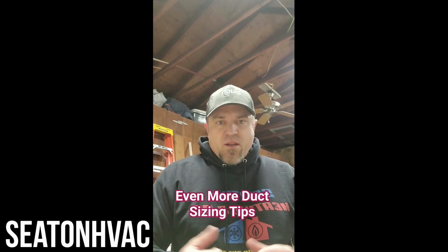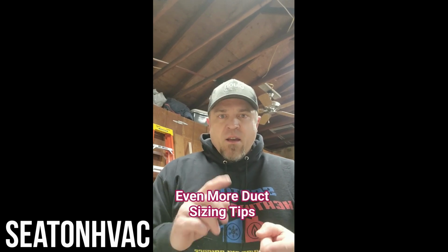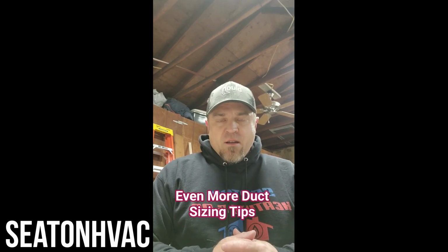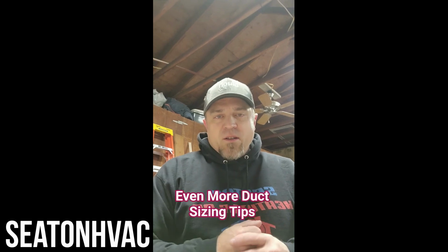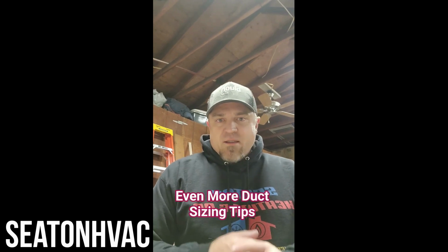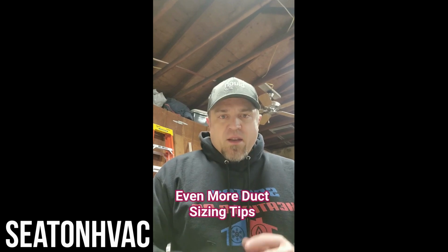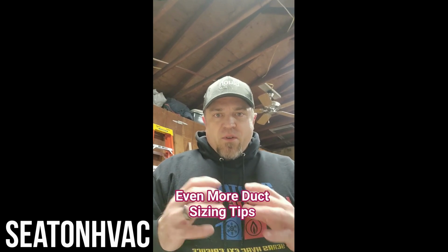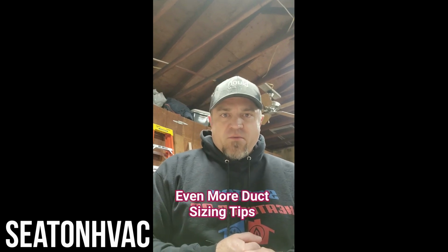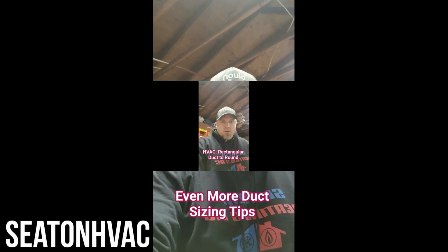So what we're going to do tonight is we're going to have some fun with return air sizing and return grill sizing, and I'm going to show you some things that you wouldn't normally know. I'm also going to start out by showing you how you convert rectangular duct to round. It's not just a matter of doing the square inches and converting it. There is a formula, because the friction rate between rectangular and round is different. There is more friction rate when you're using rectangular duct. So got some fun stuff for you tonight. Let's get on with it.